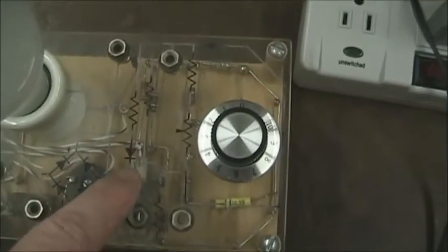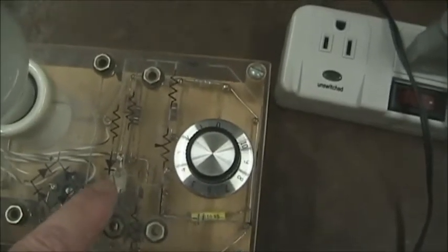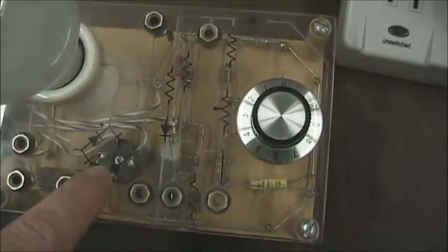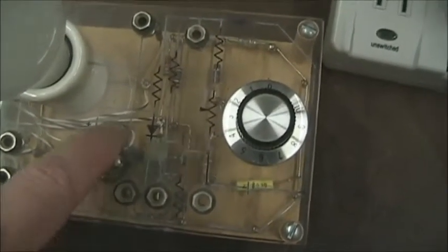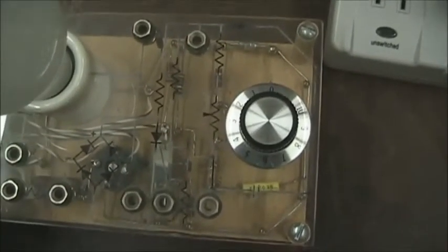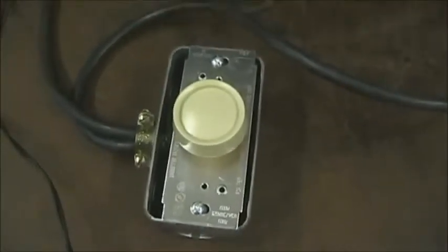Since the SCR only works in the forward direction, if I make the voltage into it from the AC rectified, then I will have positive values and I can trigger on my SCR. A Triac actually uses two SCRs in a parallel back-to-back kind of operation.